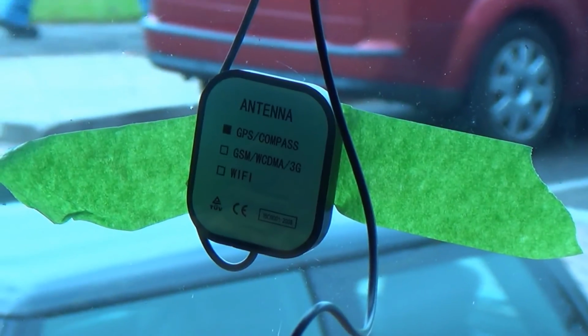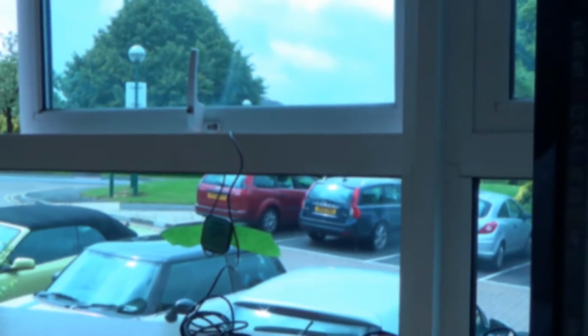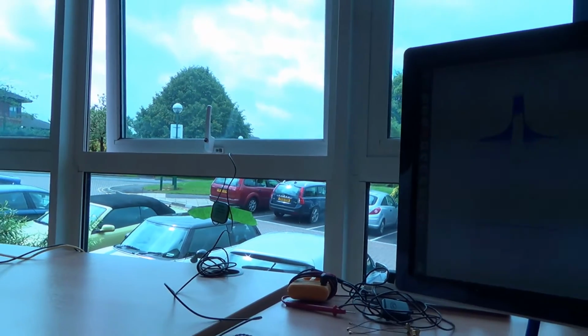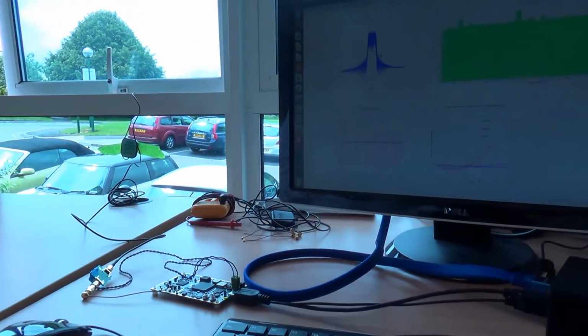The low IF configuration has the advantage of making the receiver relatively insensitive to DC calibration issues associated with zero IF receivers, but it also gives a few dB extra increase in sensitivity compared to zero IF.